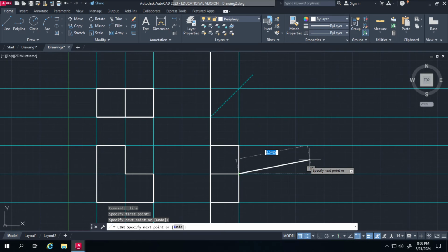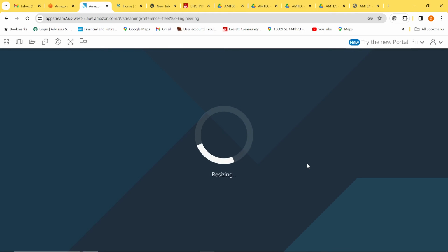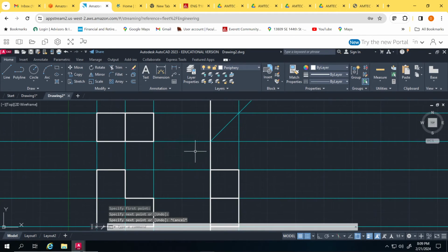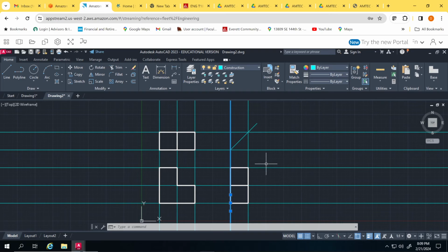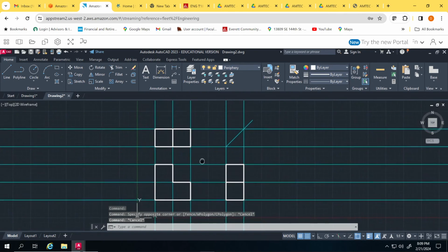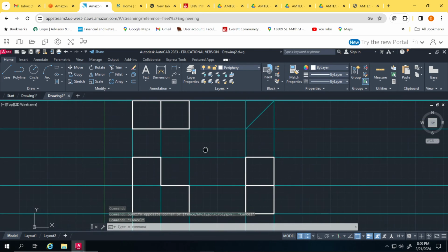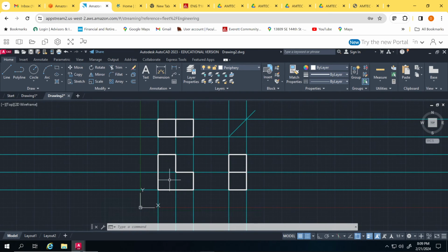Okay, I don't know what else I can do but hit escape and watch this thing do this thing. What I'll do next is, if I want this line to be a construction line, I don't have to rebuild it. I can simply select on it, choose periphery, and select construction line, and it converts that back to a construction line. I'll hit escape, and I've successfully created 3 views that all have construction lines that are projected to represent each edge.